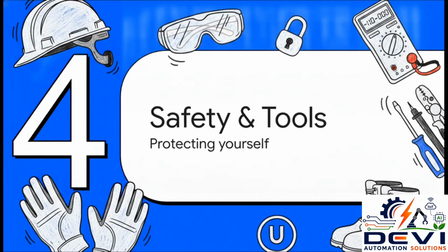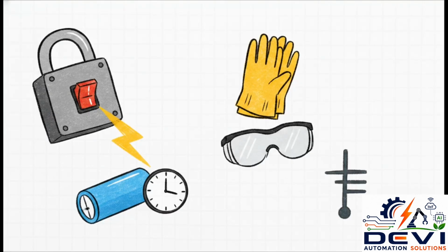Section 4. Safety and required tools. Okay, hold on. Before you touch a single wire we just talked about, we absolutely have to talk about safety. These non-negotiable safety measures are literal lifesavers. Use lockout, tagout, wait for the capacitor discharge time. Seriously, a VFD can hold lethal voltage for up to 10 or 15 minutes after you kill the power. Wear your electrical PPE, ensure proper earthing, follow safe measurement practices, and always adhere to manufacturer guidelines.